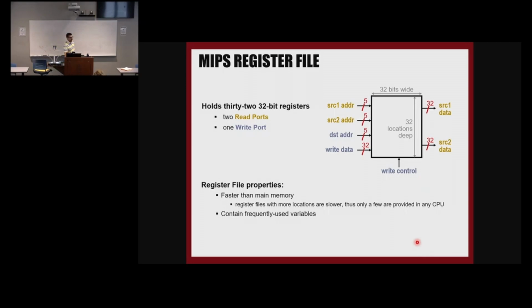So that's why we have 5 bits here, because with 5 bits, we can have numbers from 0 to 31, and that 0 to 31 is the address for each of these blocks in the register file. So the input for that addresses the memory blocks, the registers in the register file, has 5 bits.